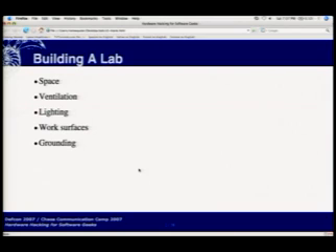One way to start is an ESD mat and some grounding bracelets. And maybe a coat if you've got cats or whatnot, because even if you've got fur on the outside of the coat, it's of a material that's going to keep the static from building up on the fur and not going to short your devices. So the coats are actually fairly useful, especially if you have pets.